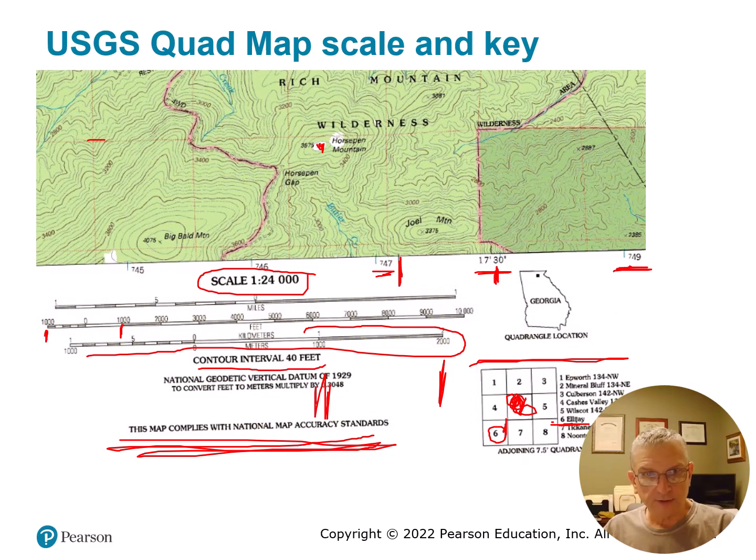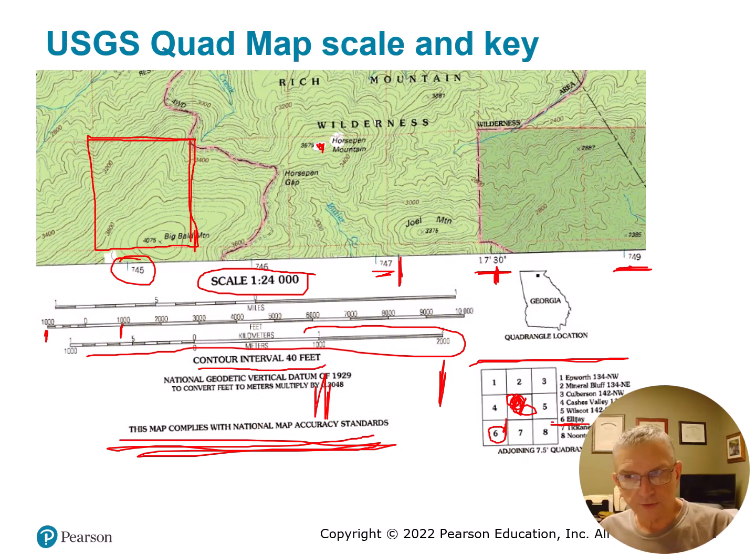And these lines in the background are actually land lot lines that have been transposed to help navigate where people are and identify property lines. And in the USPLS states out west, mostly, and in Florida, these are township sections and ranges, not land lots. But these are grid ticks if you're looking at a projection in UTM, or Universal Transverse Mercator. That's going to help you figure out where you are.